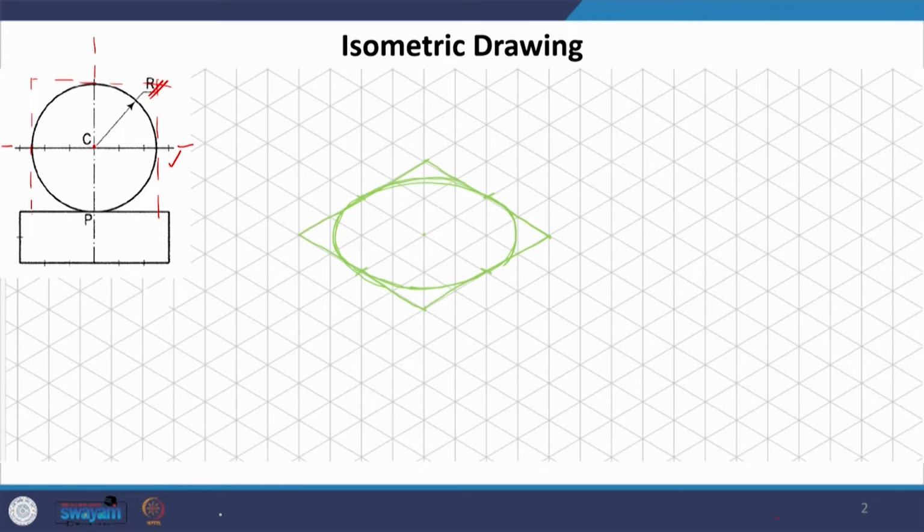Now, there is another plane which is cutting the same sphere, passing through the same center of the sphere, but vertical, perpendicular to HP and parallel to VP. So, this square is going to be here. If you draw it, this is where your second square is going to come, which will contain the circle which we will now see. So, this is a horizontal circle which is generated when we cut the sphere into two halves by a plane which is parallel to HP and perpendicular to VP.